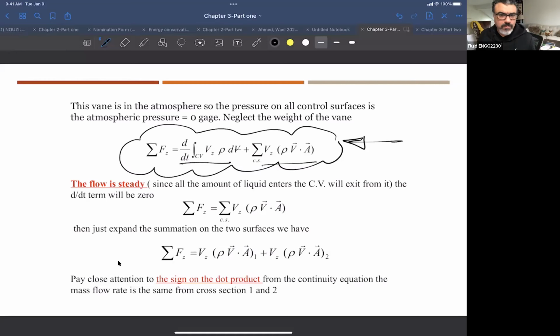So it's going to be much more complex than what we are talking about here. But you can imagine now, for a steady state problem, it's going to be only mass times velocity coming in and mass times velocity going out. The difference between these two will give you some forces, and this is a simplified equation out of this.